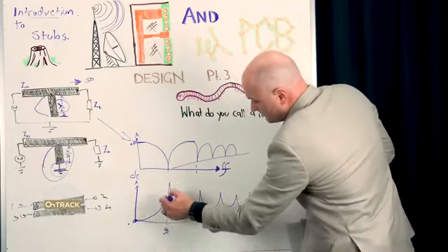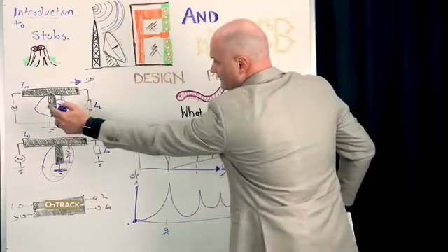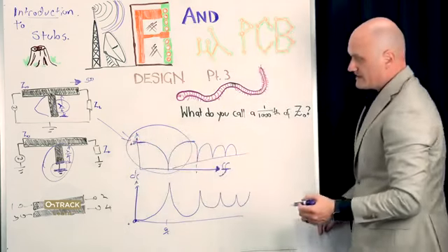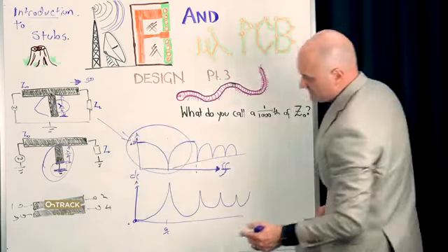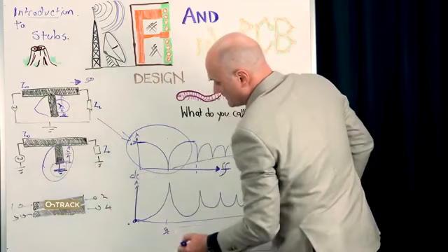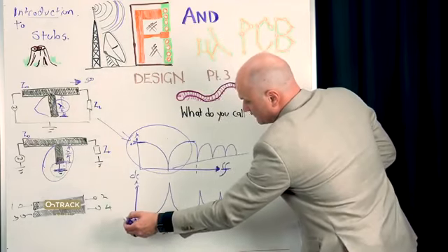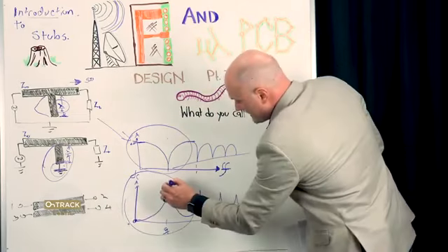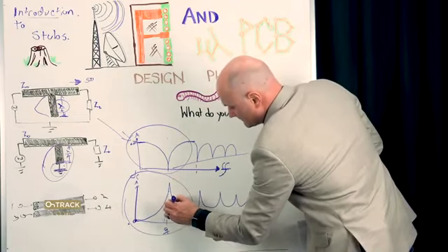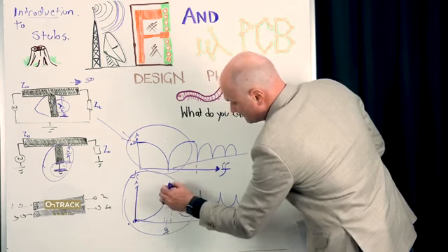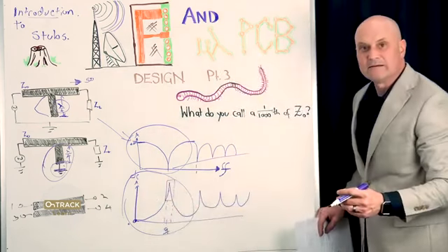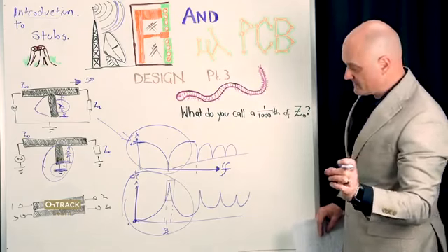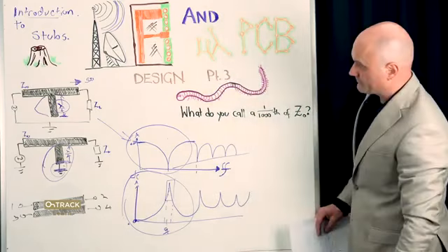And so the open circuit stub in its crudest form is a band reject or notch filter. The short circuited stub in its crudest form is a band pass filter, but they're very narrow band devices. So the range of frequencies that get passed here is only within, maximum 3% of the center frequency, typically.